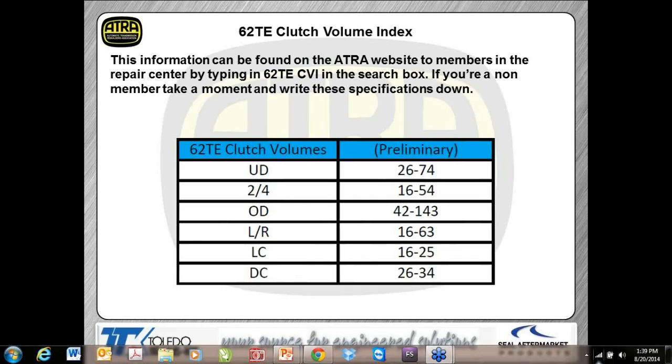Now once the Sprague's on there, obviously if you hold the inside and you turn the outer race, it should go counterclockwise. And there's also an ID groove here, and that faces up when it's installed correctly. So just like the general rule on most ID marks, obviously you want to be able to see the ID marks as you're assembling something. So the ID groove, it should be facing up.